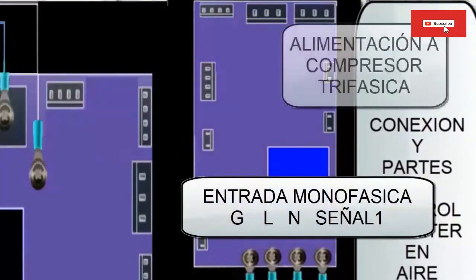Once powered, it is the same external card that is in charge of feeding the compressor with a new voltage of the three-phase type. This three-phase supply voltage can change its value and frequency. For this, the outdoor card reads the values taken by its sensors, and the information brought by the signal cable, which comes from the indoor unit.